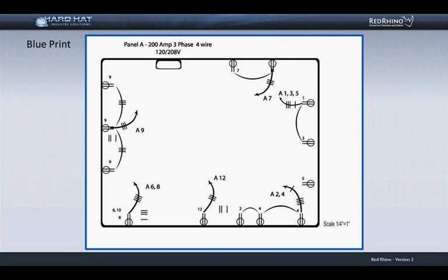I take off conduit at right angles and allow enough conduit to go around obstacles or obstructions in the building. I also allow for riser length by over-rolling past the end of the conduit run. When you roll past, it adds extra length on the scale X count. For consistency, I take off branch conduit in a specific order. I start by taking off EMT conduit, then I take off all the MC cable. Now it doesn't matter what order you do the takeoff, just as long as you do the same order every time. It gives you consistency.